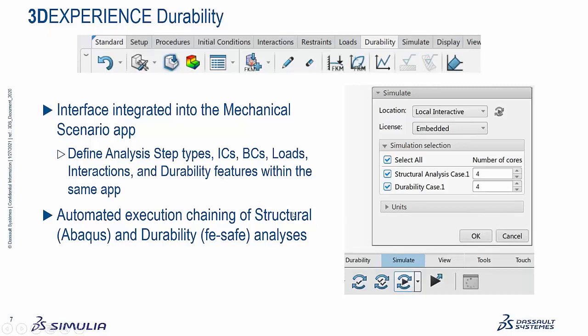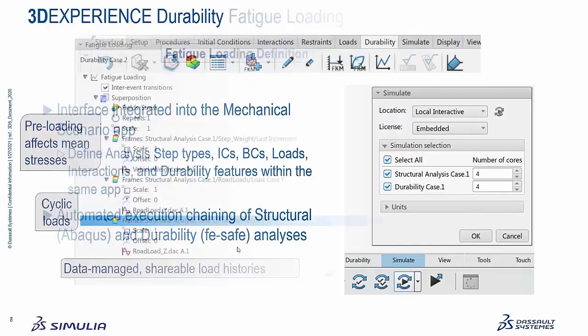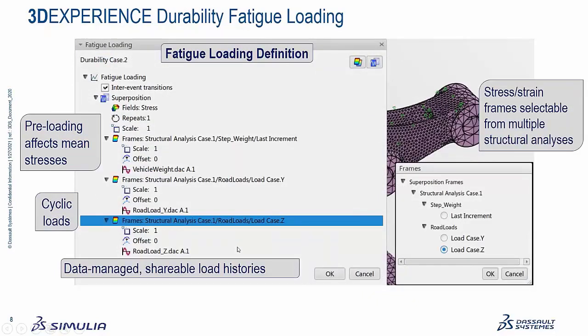The structural simulations, of course, run Abaqus in the background, and the durability calculations are actually running the FE-Safe fatigue engine in the background. So we can cover, at this point, almost all of the fatigue loading options that are in FE-Safe within 3DX. You can actually set up load histories in the PLM system and then share them amongst multiple simulations because they're in the data management system.